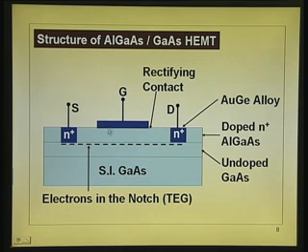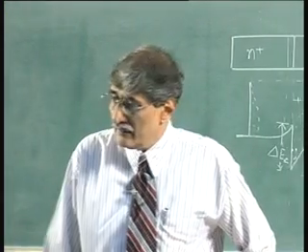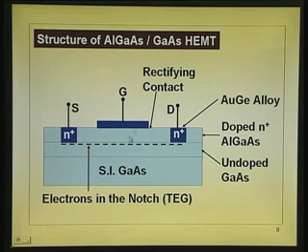You have a metal semiconductor rectifying Schottky barrier. So, you can see the Schottky barrier haunts us everywhere now. Okay. In the case of gallium arsenide based technology, you have that metal semiconductor contact, which is rectifying. So, there will be depletion layer across this. More about the impact of that we will see little later, but right now there will be depletion layer width. Now, you can have the depletion layer width chosen, or you can have the thickness of this layer and doping adjusted such that the entire layer is depleted. Entire layer is depleted. If the entire layer is depleted, that is what we plotted. Whole current will be there. It is equivalent of metal oxide semiconductor.